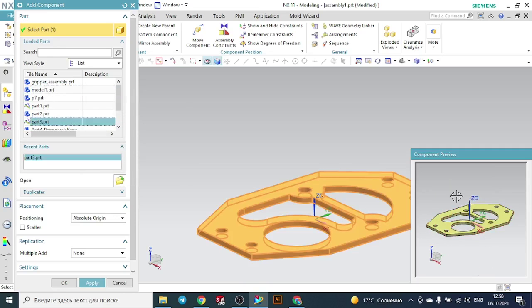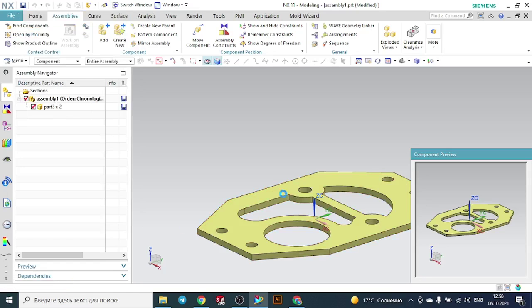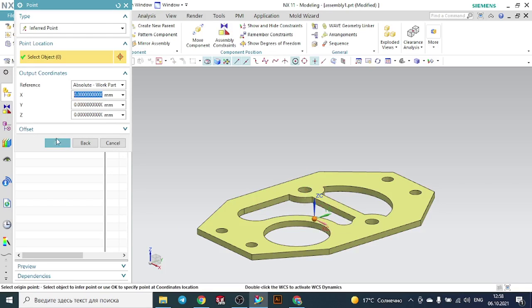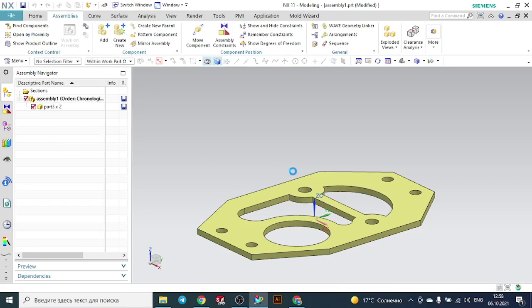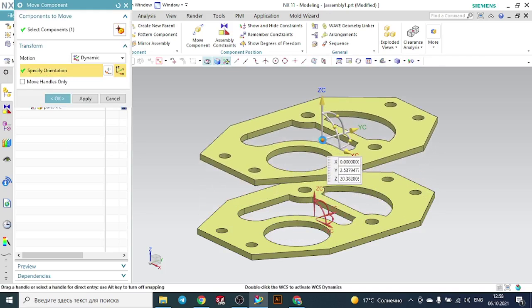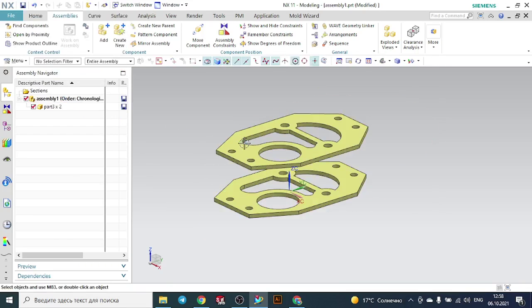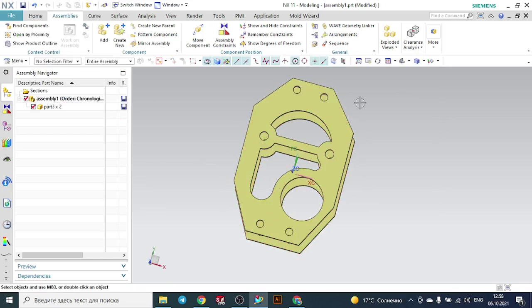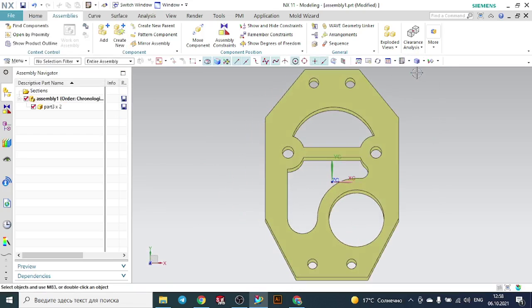You see here it is the demonstration, and here I will select, for example, the move positioning and press OK. So the point is created here, press OK. It will be loaded. So it is loaded. I can move it. You see the second one is to move. Now I will make the constraint, that is, make the assembly between these two elements.